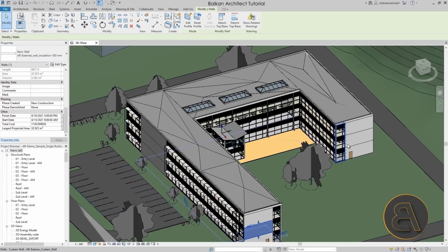And then also I have shown you how to use the data from the Bexel Manager to import that back into Revit. So you can manage the projects, and you can create these animations, and then you can import that start and finish and total cost data back into Revit.